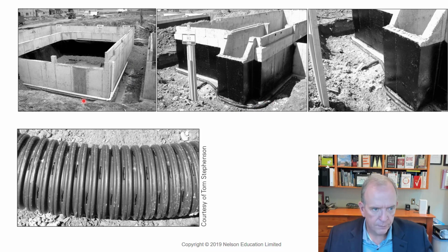So this is going on top of the footing. The weeping tile goes beside the footing. Very often this piping system is not used. Very often what municipalities want is that water to drain out onto the surface area and be absorbed by the local ground. It's less taxing on rivers and lakes and that sort of thing, anytime you can get the local ground area to absorb the excess moisture.